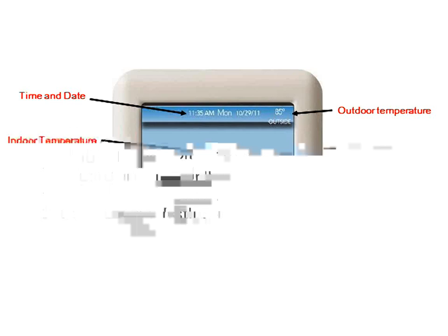If you choose to use one of those optional remote sensors, which you can certainly do, right? So maybe their thermostat location is in the dining room, and pretty much nobody uses their dining room. That's been my observation. I certainly don't use mine. And you want to sense temperature in your family room where you basically spend all your time. You can leave the thermostat where it is and all of its wiring to the equipment and leave all that alone if you want, and then put a remote sensor anywhere else in the house that you pick.